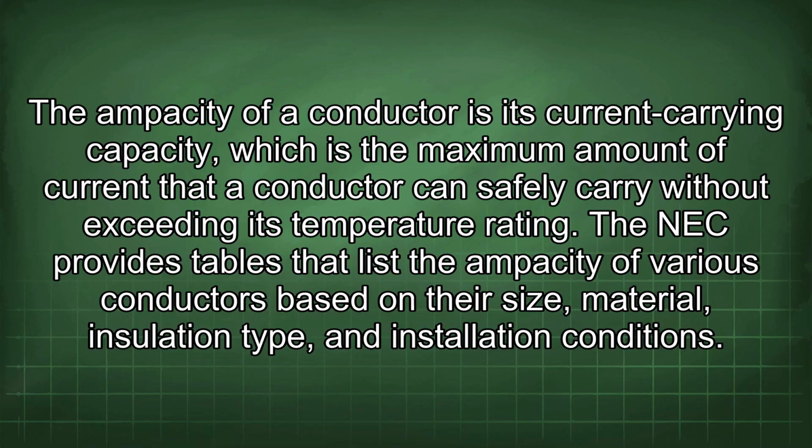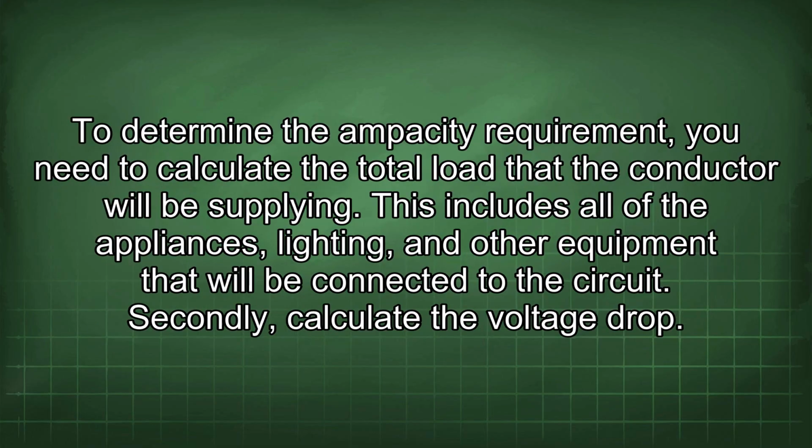The NEC provides tables that list the ampacity of various conductors based on their size, material, insulation type, and installation conditions. To determine the ampacity requirement, you need to calculate the total load that the conductor will be supplying. This includes all of the appliances, lighting, and other equipment that will be connected to the circuit.